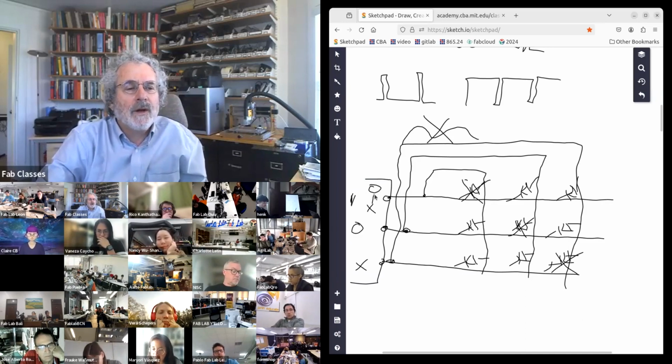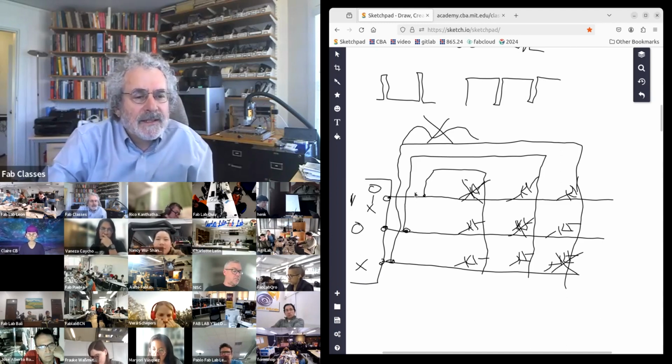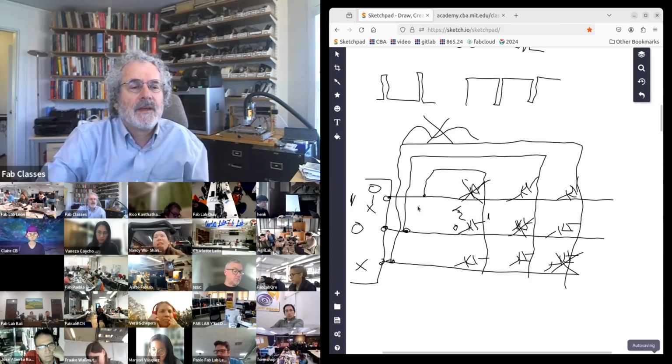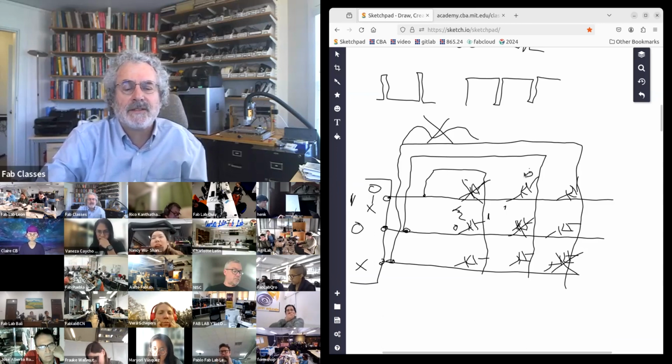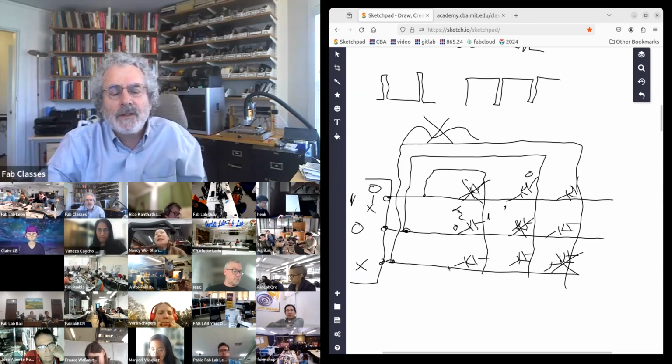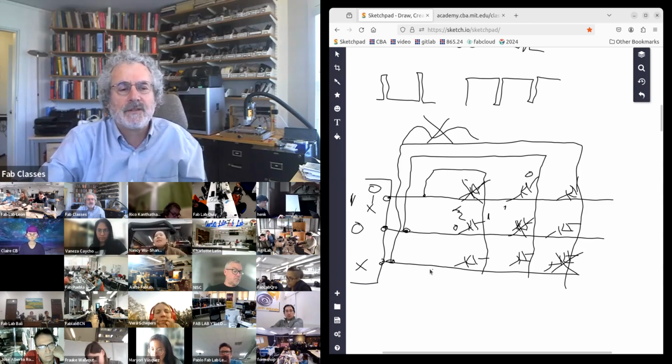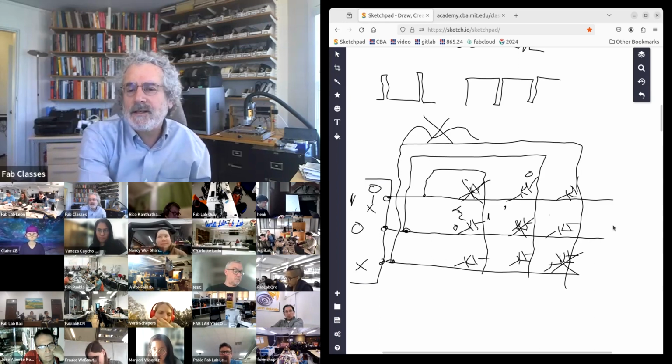So the 1 going here and the 0 here, if we follow, we have a 1 here, we have a 0 here, and so this LED turns on. That's great. In addition, we have the 1 here, we have the 0 here, and nothing happens because the LED doesn't go backwards. And then this one is just the tri-state, and so nothing turns on. So we turned on only one LED.